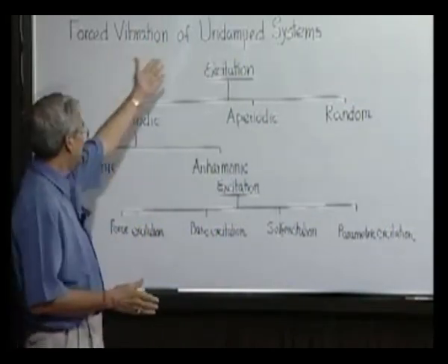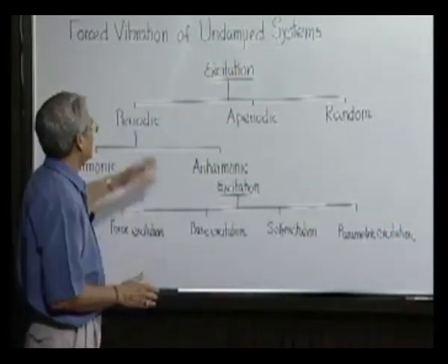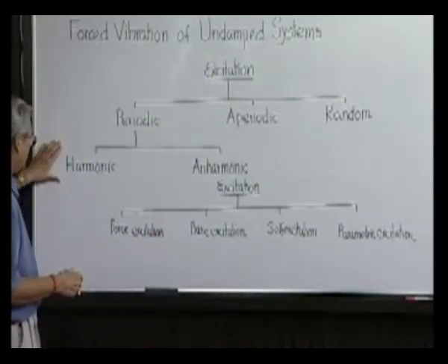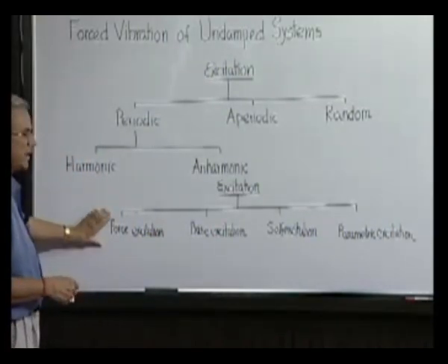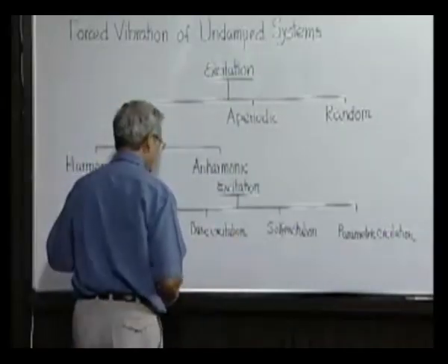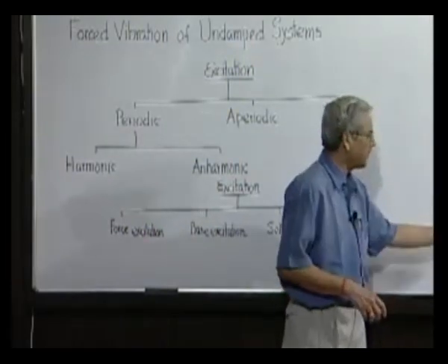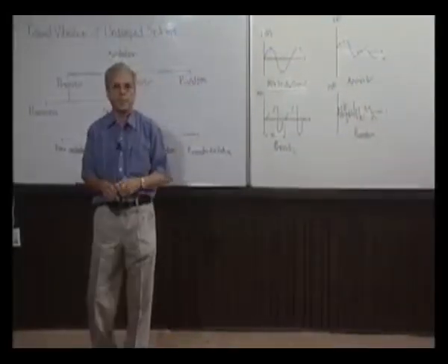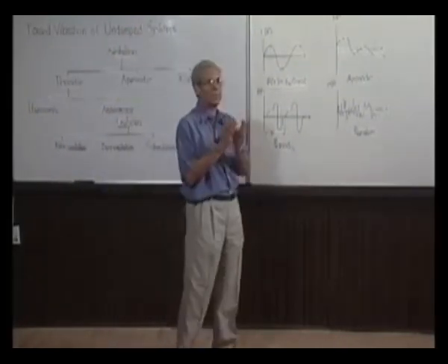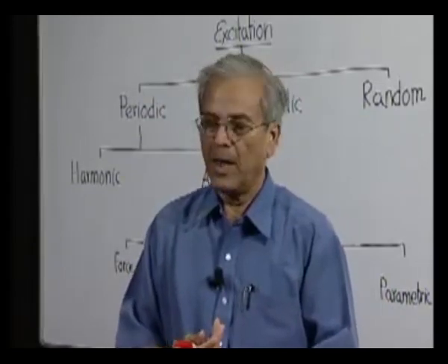We have taken the simplest system, an undamped single degree of freedom system, and for the excitation also we will take the simplest, that is harmonic excitation, given in the form of either a force or a moment. Another reason why harmonic excitation is a very important problem is that any kind of periodic function of time can be represented in terms of a Fourier series, where each term or component is a harmonic function of time.